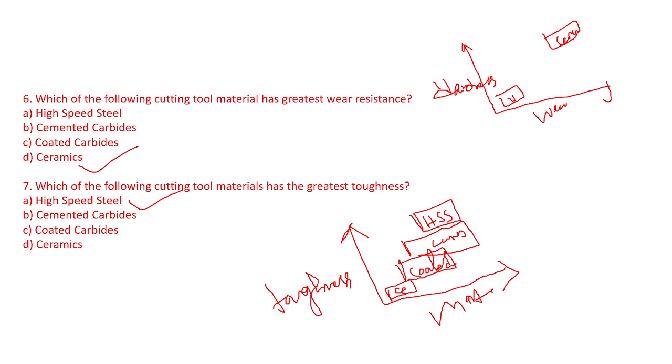Choose the grade with the lowest cobalt content and the finest grain size consistent with adequate strength to eliminate chipping. Tungsten carbide grades are used for heavy cuts in steels, where high temperature and high pressure deform the cutting edge plastically. So these are some of the advantages why people have used cemented carbides as cutting tools for a long time.